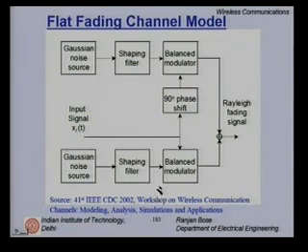This is an exact depiction of that. So, we have a Gaussian noise source and another independent Gaussian noise source here. Right. Here we have a shaping filter, a balanced modulator with a 90-degree phase shift, so cosine and sine, and then multiply. This is nothing but your Rayleigh faded signal.